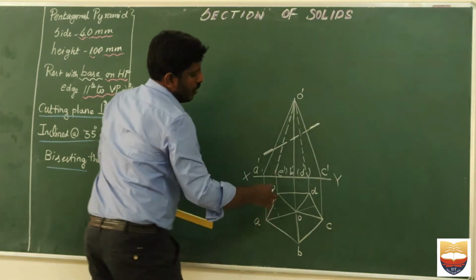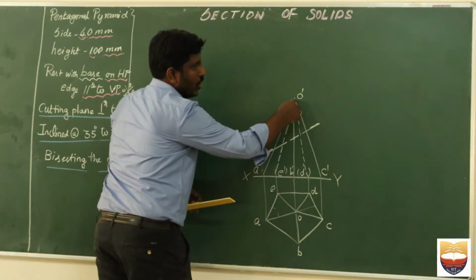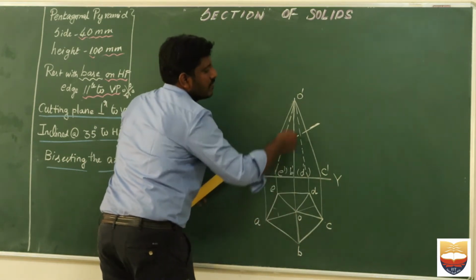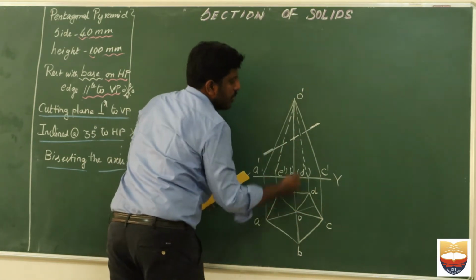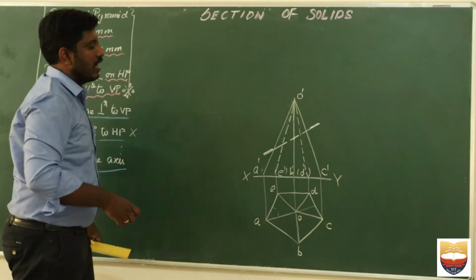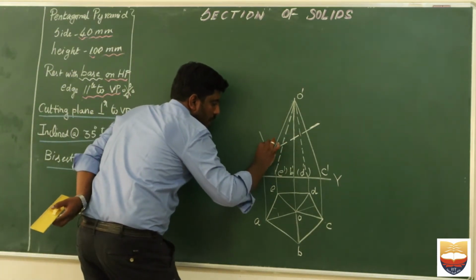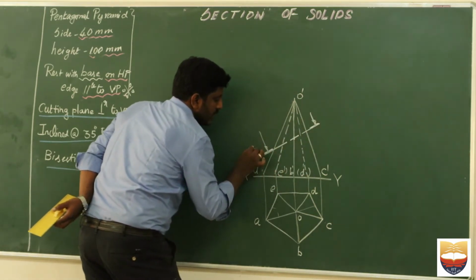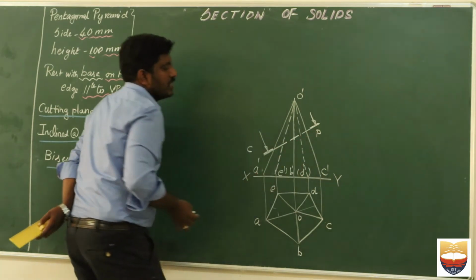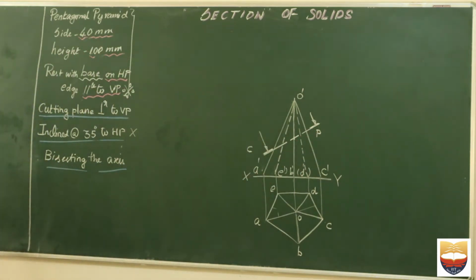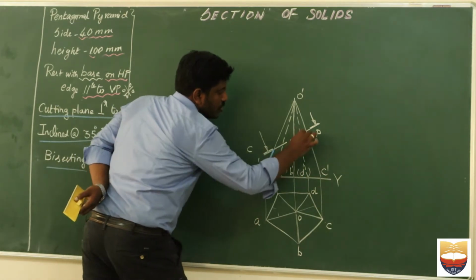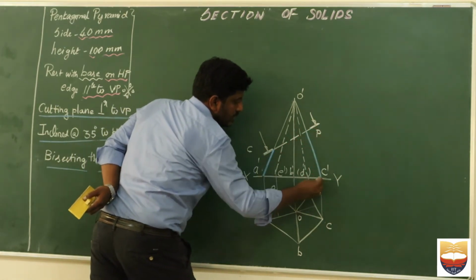So now I hope you understood one more concept here, why this B to O is darker instead of a center line. Hence B and O come in the same line. The concept is I have to show B to O. That is the reason why I have drawn like this. Okay, so then obviously I know that I have to draw a perpendicular line with the arrowhead, and I have to name it as CP, which means cutting plane. And you know that obviously only the object which is below the knife should be darker. So that is the concept of your section of solids.